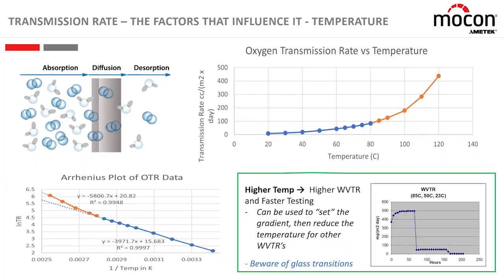really near 85-90C. What's going on there is the material is changing, given that this high temperature is now doing something to it. The most common thing for the material to undergo is something called a glass transition point, where it changes form a little bit. Maybe it's more plastic or elastic now under this very high temperature condition. So the material's changing, and if the material changes, then how the molecules diffuse through it will change too, and it really takes off.